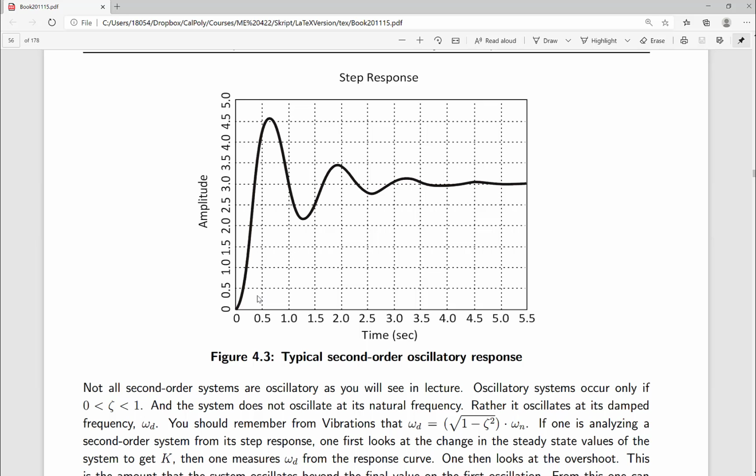You have failures because the people designing them design for one temperature and then move it to another, but they fail to recognize that in going from one temperature to another, or one pressure to another, or one location to another, it may actually overshoot beyond the aim point. And if you haven't designed the system to handle that extra room or pressure or tank height, then you can have a problem.